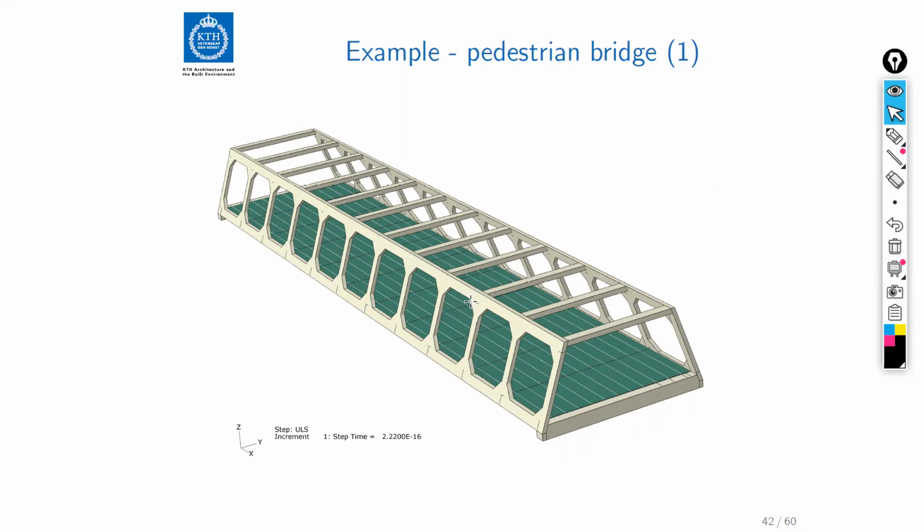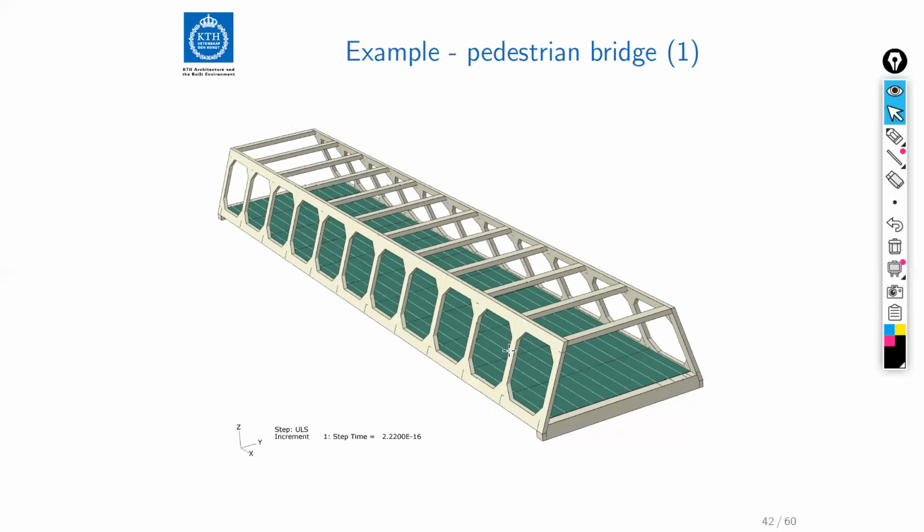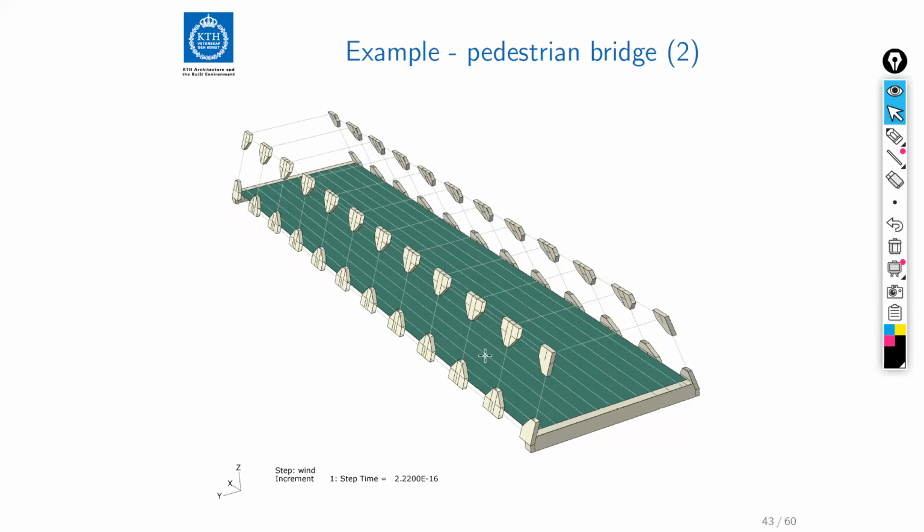So that's safe. So they adopted the strategy of trying to design this bridge so as to get the frequency of the fundamental mode above 5 Hertz. They made a lot of effort to do that, and made some quite interesting mistakes in doing so. When I got this problem, I thought there is no way for us to make this bridge have a frequency above 5 Hertz unless we make ridiculous adjustments to the structural system and put in a lot of material that is totally redundant and useless.